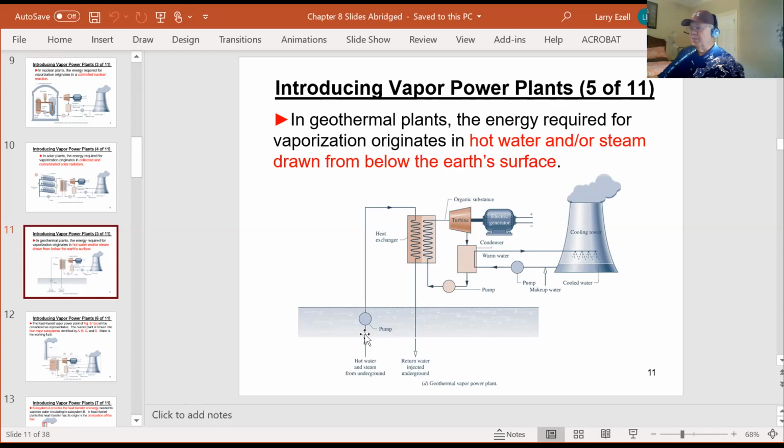Then the pump would pump up this hot liquid, go through a heat exchanger, then return back to the well, and this would be a boiler. The water would never touch the Rankine cycle water, not physically, but thermally they were in close contact. So you transfer the heat from the hot geothermal fluid into the boiler, produce steam, and go on with your conventional Rankine cycle. We spent millions of dollars on that and finally developed a pump.